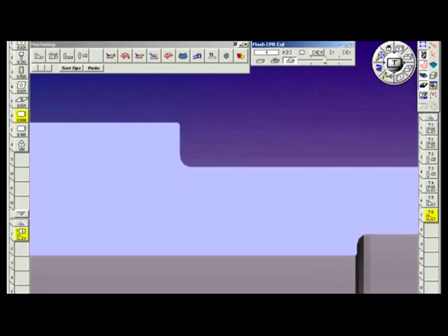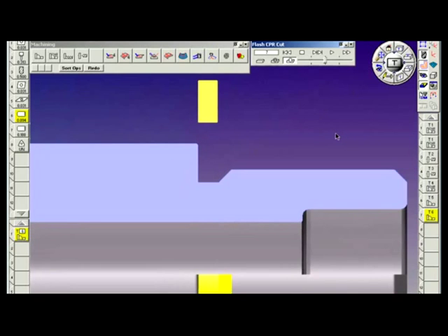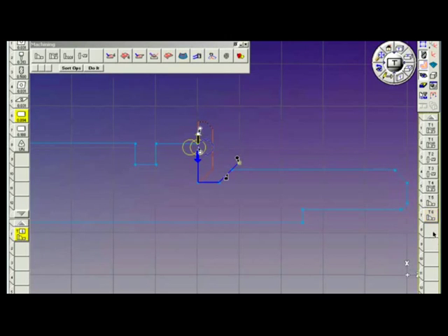If you notice with the no drag option, the cutter comes in, positions, cuts down, retracts, repositions, cuts down the angle. Now it cuts across the bottom and leaves the work in that manner, not pushing all the extra material down here. This comes down and then down this way and across. Show the geometry, and there it is. Turn off rendering, deselect the operation.